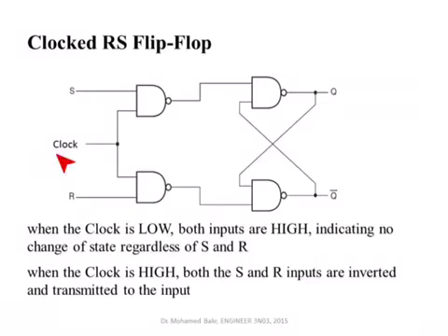Okay? So you can see everything here will be dependent on the clock going high. So you can have your clock, and at the moments when the clock is high, these are the only moments where you can have a change in the value of the flip-flop. When the clock goes low, the output of the two NANDs will be 1, resulting in a do not change condition. So whatever is in the memory will be stored in this memory.